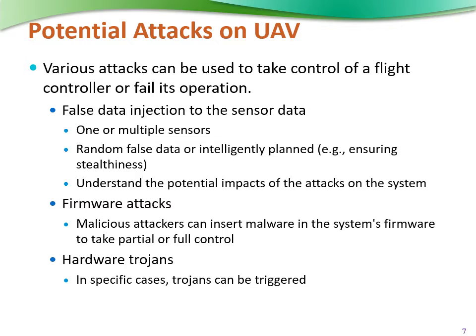The last kind is hardware Trojans, as we discussed initially. It is hard to test or validate that a device is hardware Trojan free, because it is a special circuit that is triggered only in rare cases. From the input and output of a device, it is hard to understand whether it has any hardware Trojan. Once it is triggered, the on-time and off-time of a PWM signal can be maliciously modified to result in undesired behavior.